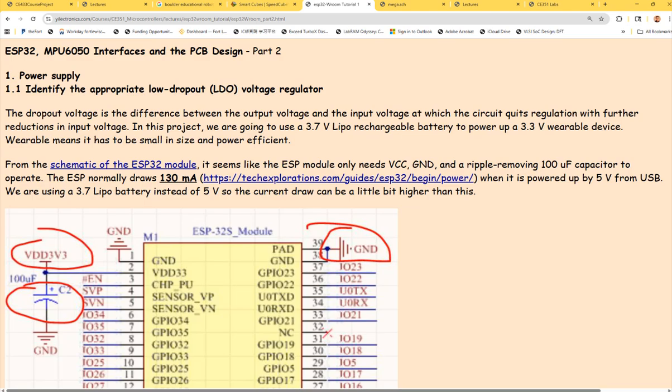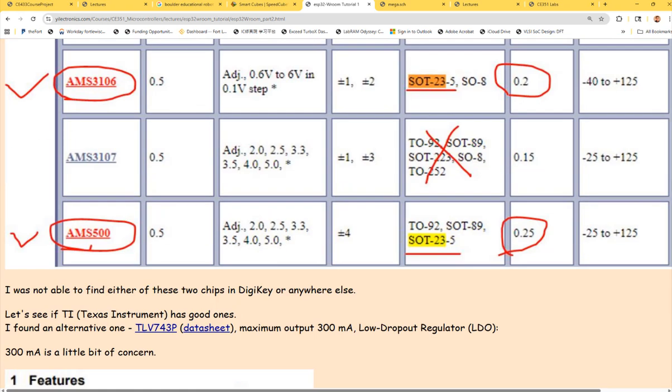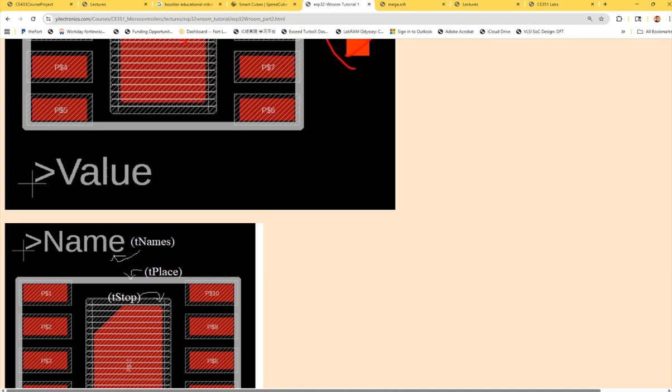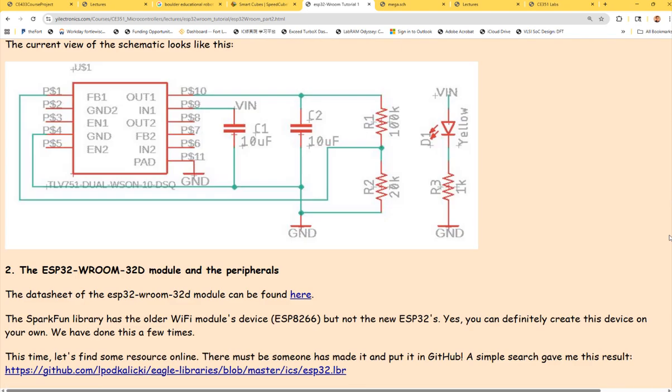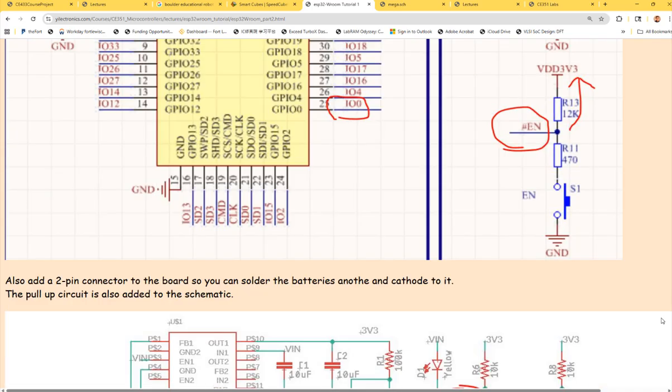So it has to be wireless. There are multiple ways to do it, but eventually we found the Wi-Fi protocol will be the best. So we chose the ESP32, and we have to design a really portable and compact PCB. It's tiny, which can fit into the bottom of the hoof.